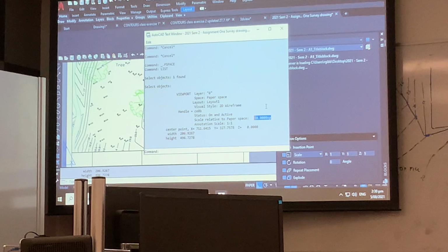I put a manhole 100 mil over on someone's boundary. It doesn't sound like much. It wasn't even the lid, the lid was fine. The manhole's 1080, and it was 100 mil over a boundary. The contractor got told immediately to move it.